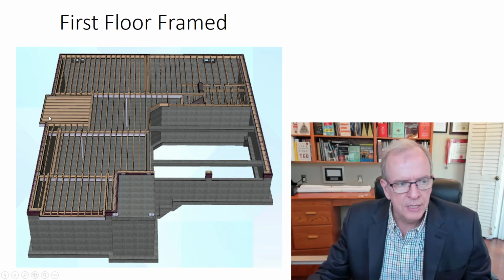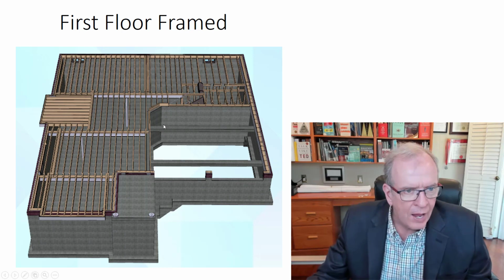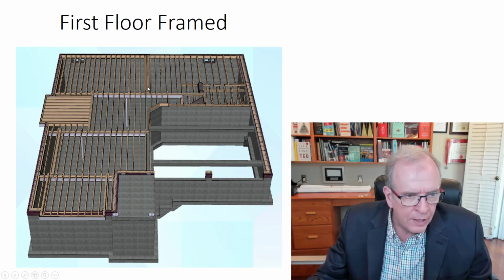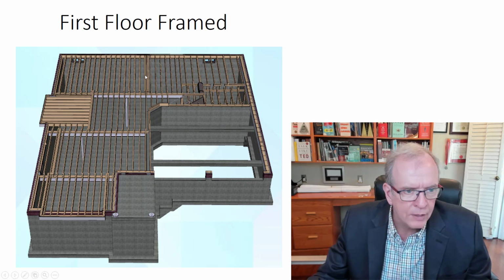So here we can see these joists. They're cantilevered out of the wall, so that's cantilevered. So are these joists out here cantilevered. So you get a good idea of how the joists are placed. Here there's a built up wood joist, and that's to support a point load from up above.